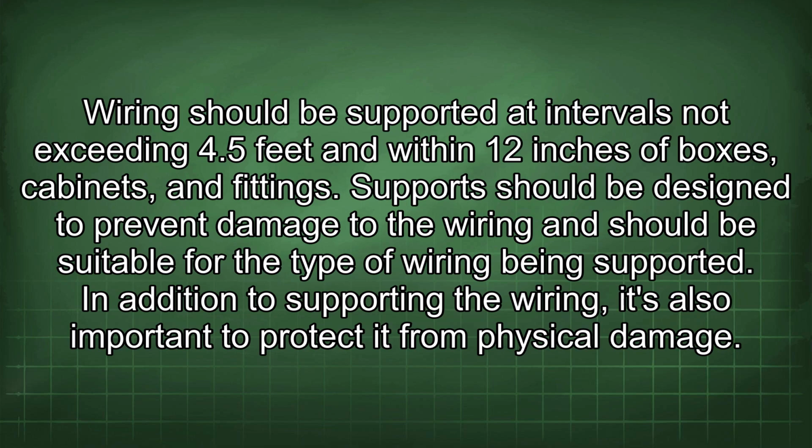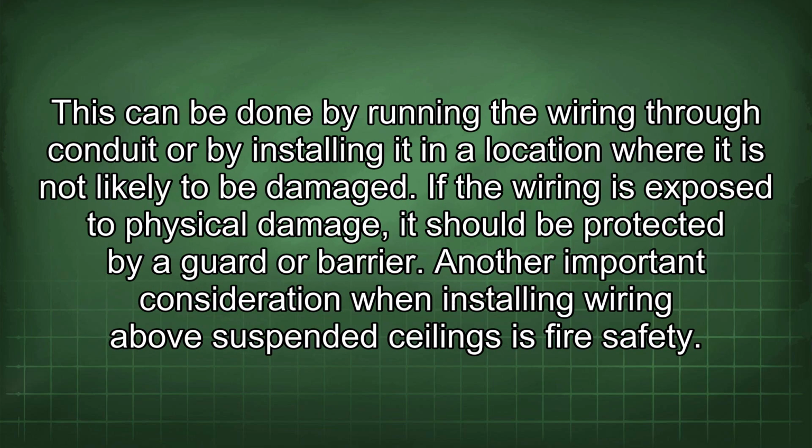In addition to supporting the wiring, it's also important to protect it from physical damage. This can be done by running the wiring through conduit or by installing it in a location where it is not likely to be damaged. If the wiring is exposed to physical damage, it should be protected by a guard or a barrier.